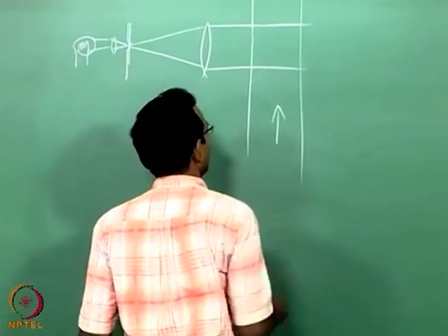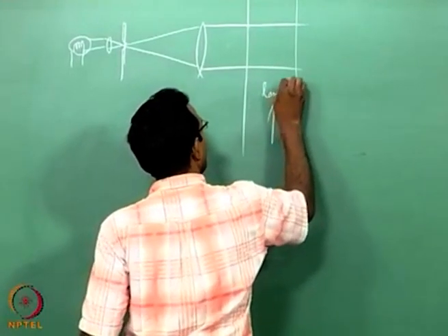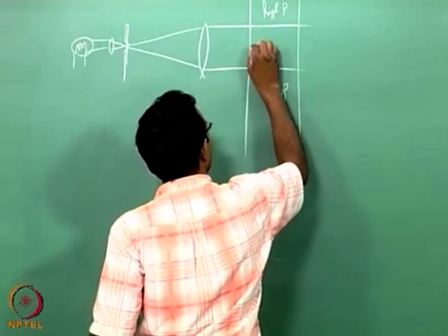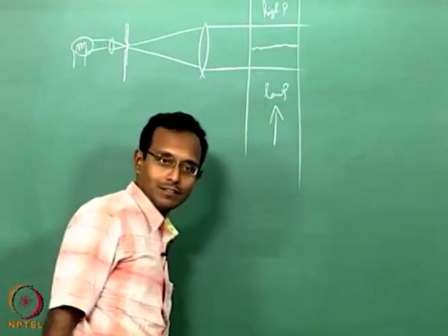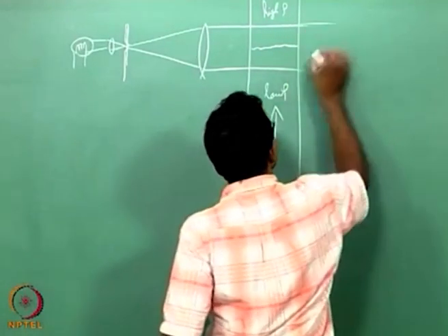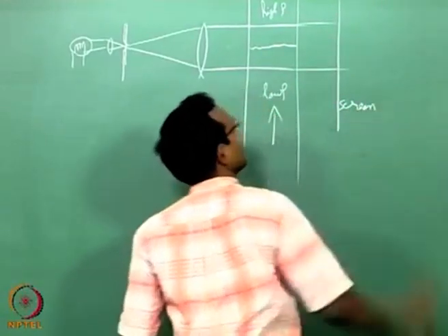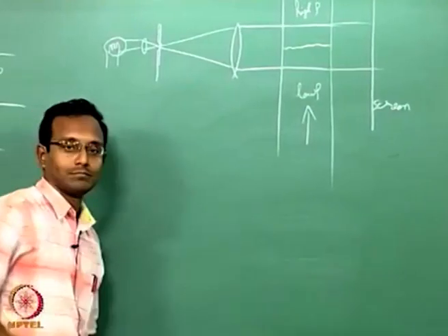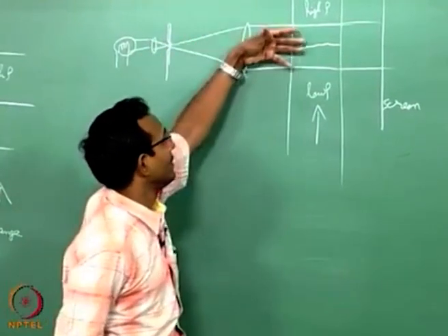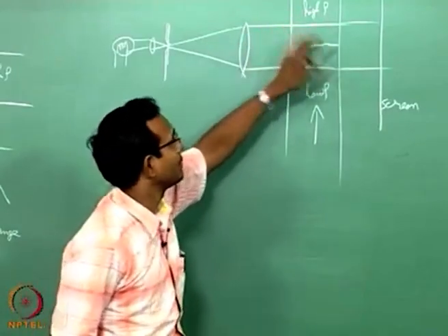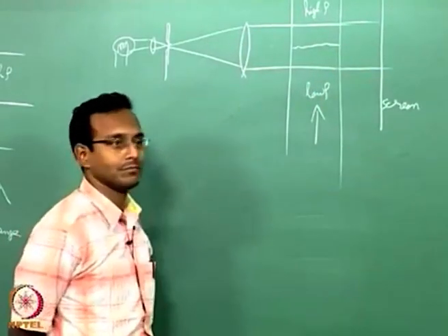Say the flow is going this way, low density, high density, and this is somewhere where my shock is present or something. Then on the other side, I will just have to put a screen. This is simple enough setup. Parallel beam of light coming in through the test section perpendicular to the test section walls, and it comes out the other side and it will be like this.